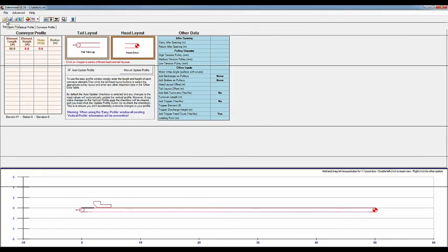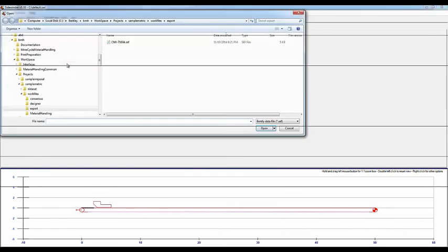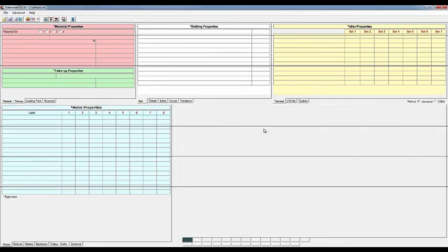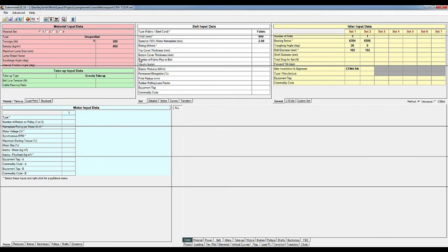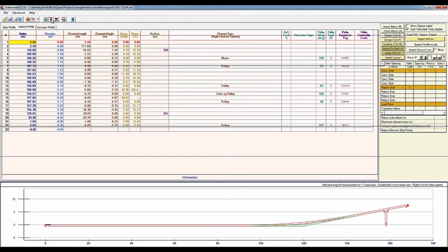In this situation, the dedicated conveyor design application is Sidewinder. The material data, belt data, and also information relating to the head and tail configuration selected are shown here as pulley and motor information. A profile of the conveyor is also displayed.